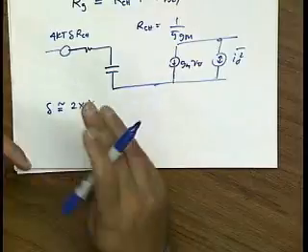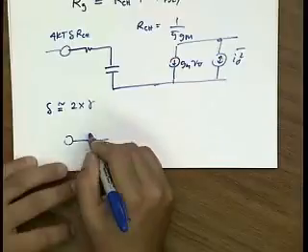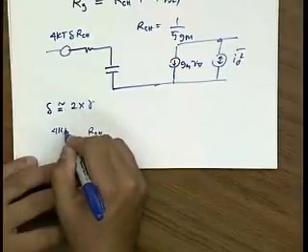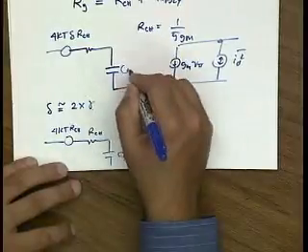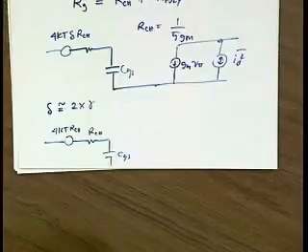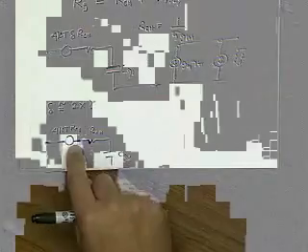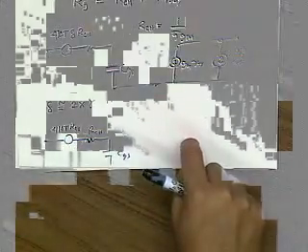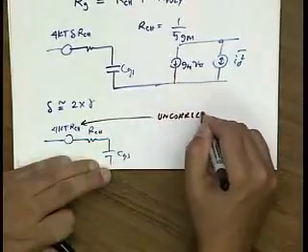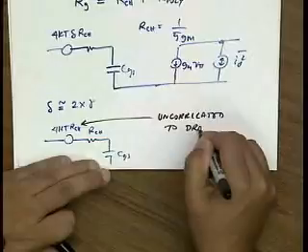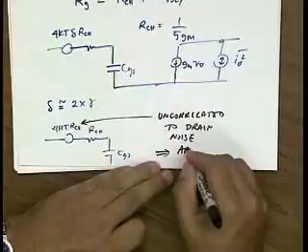Now the nice thing is that if, on the other hand, you assume that this resistance is a white noise of just 4kT R channel, and assume that delta is 1, but that this noise is uncorrelated to the drain noise, then you get the right answer, or approximately so.